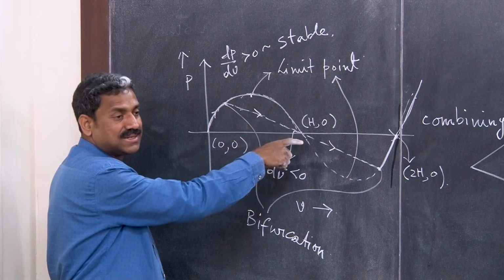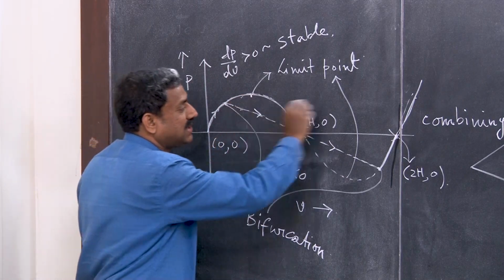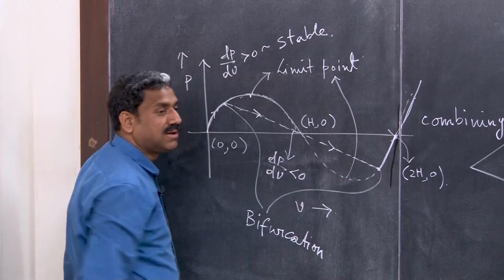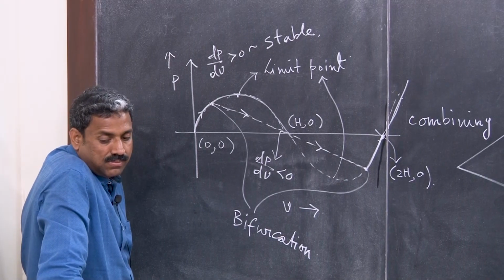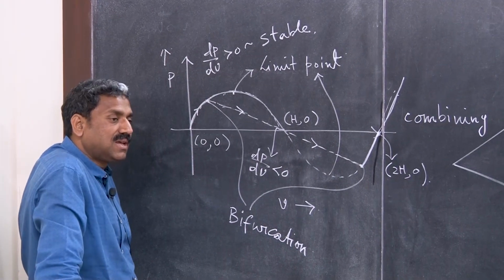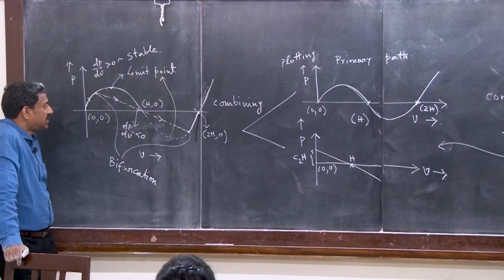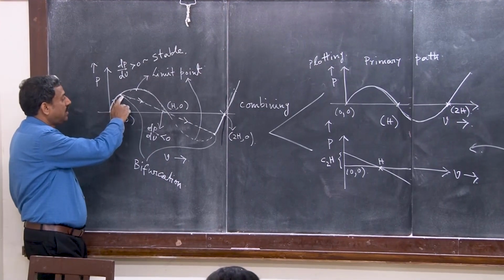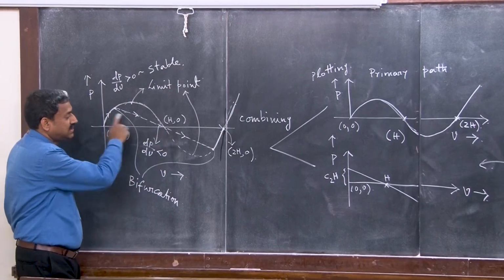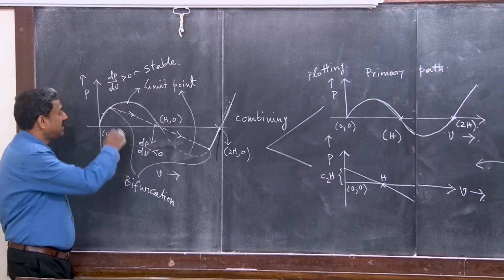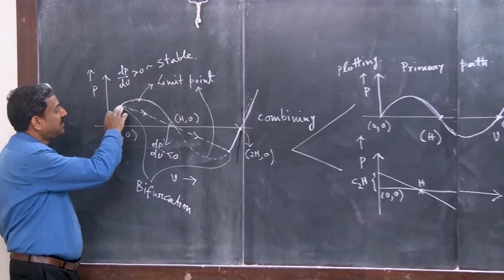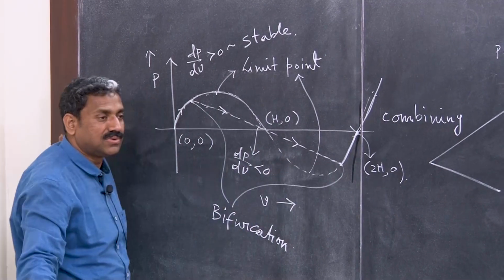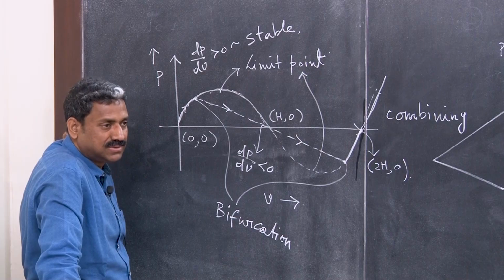Whether this is stable, this is unstable, okay. So, if you reach the limit point, it will suddenly jump and snap through. If you go here, then from this point, it will go there, okay. So, it shows coupled bifurcation as well as snap through, right. Somehow you have to restrain the system to achieve this, so that it does not follow this path, okay. Because otherwise, if you follow this path, it will gradually follow these things, okay. But it is an unstable path, okay. Please note that.